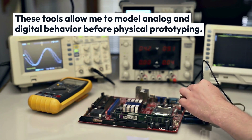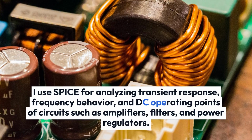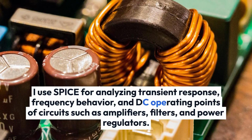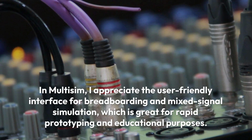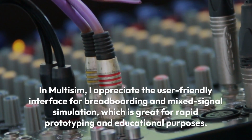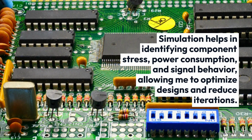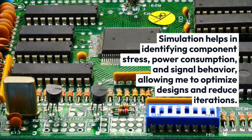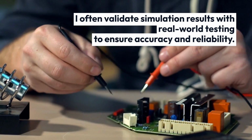These tools allow me to model analog and digital behavior before physical prototyping. I use SPICE for analyzing transient response, frequency behavior, and DC operating points of circuits such as amplifiers, filters, and power regulators. In Multisim, I appreciate the user-friendly interface for breadboarding and mixed signal simulation, which is great for rapid prototyping and educational purposes. Simulation helps in identifying component stress, power consumption, and signal behavior, allowing me to optimize designs and reduce iterations. I often validate simulation results with real-world testing to ensure accuracy and reliability.